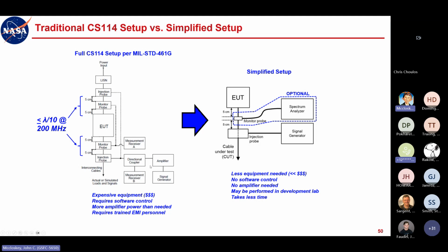It's not the best idea to rely on a software control loop to limit the injected power. You want some hardware limit on the available power that you can inject. With any susceptibility method, there is always some tangible risk of damage, and you need to control that in as many ways as you can. So controlling the open circuit potential and the short circuit current are certainly important parts of that.